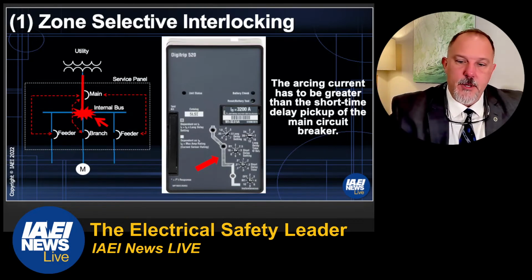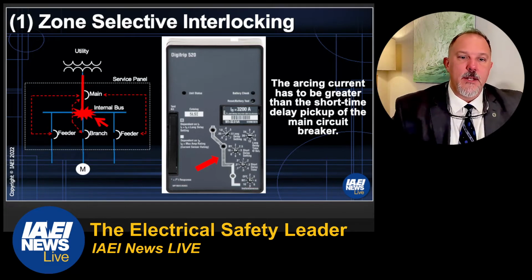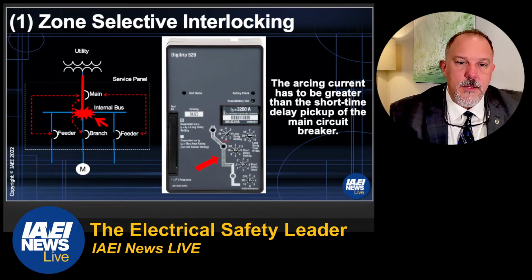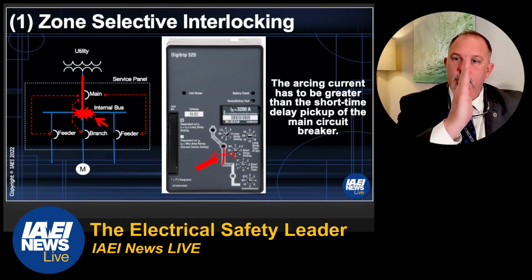And there's your trip unit and that set point. So here is the set point right here. This is established as your trigger point because that set point controls this portion of the trip curve, whether it is left or right. That's what that dial does. It moves the curve left and right.